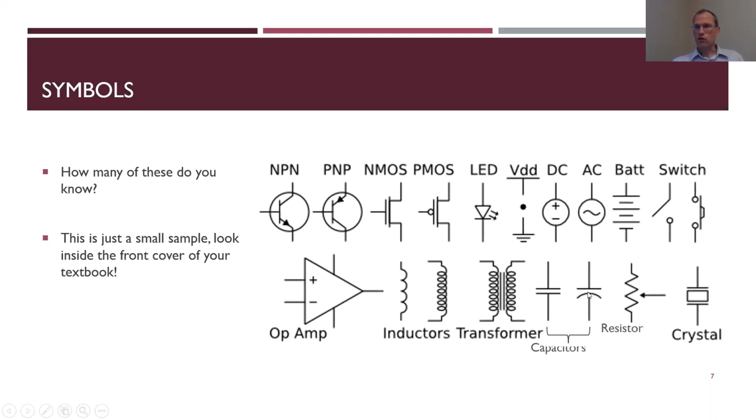So with these you have to be careful, because if you hook them up backwards, they blow up, and I have seen that many times in lab. Resistors, again, a few different types of those. These are just the more common ones, the ones that we'll probably be seeing most of in lab. I don't think there's too many other than this we'll see in these next 8 weeks, but there's a whole bunch of them. The front cover of your book has a ridiculous amount of them that you could possibly see.